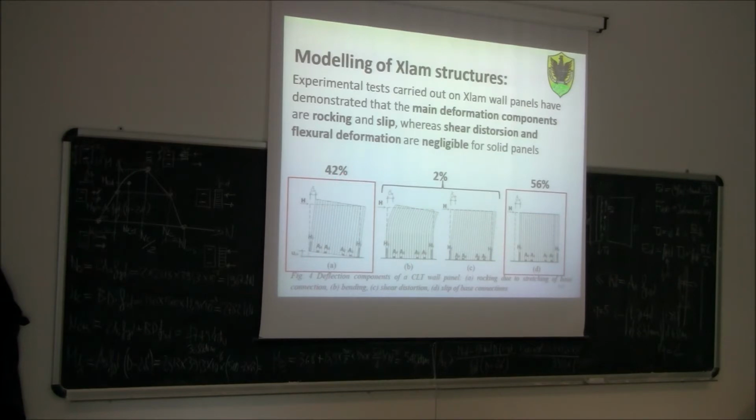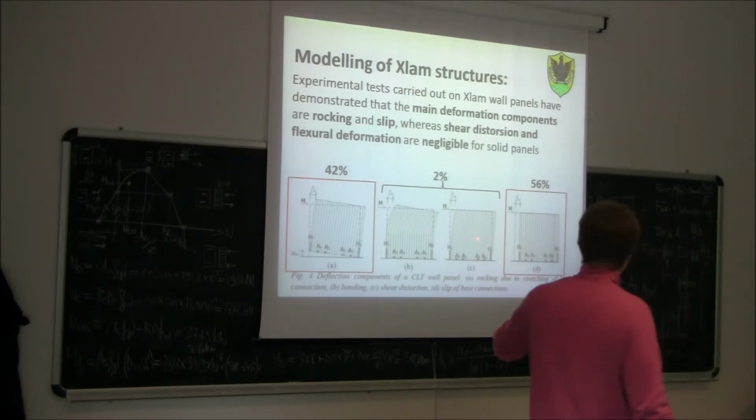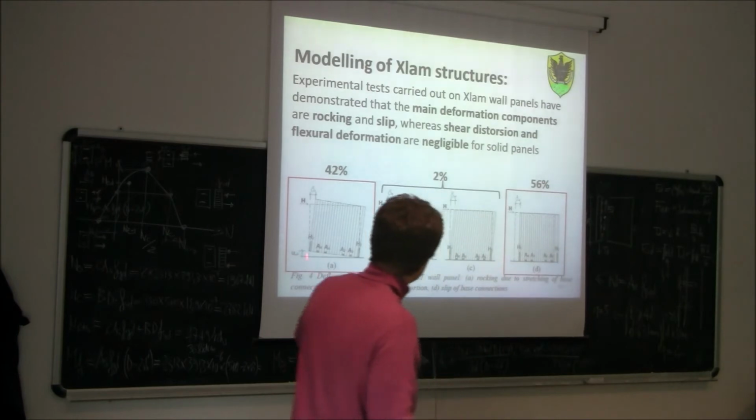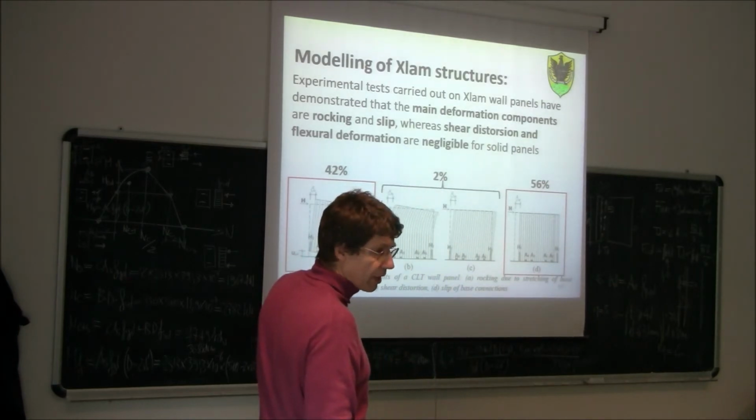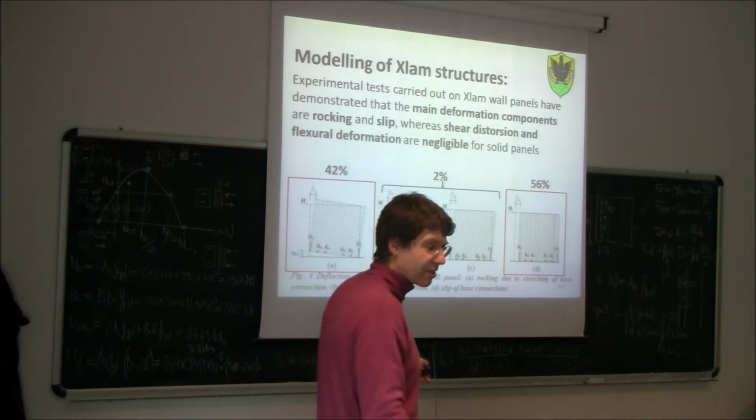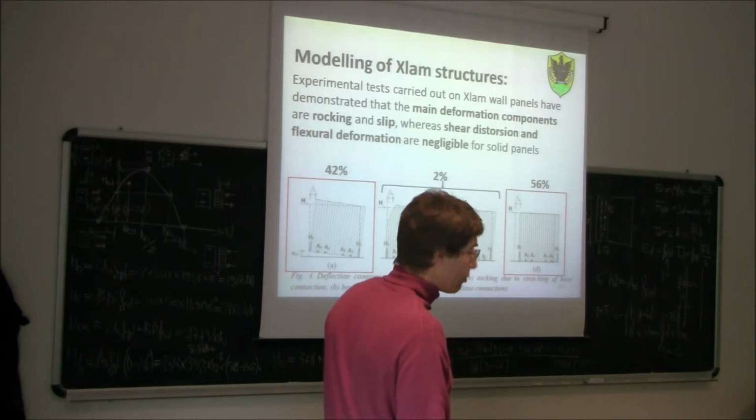So just keep in mind that if in the future you have to model multi-story timber buildings, it's okay, you can also use the shell elements for the wall, but then you need to remember to model these connectors with springs, because otherwise your model doesn't make any sense.